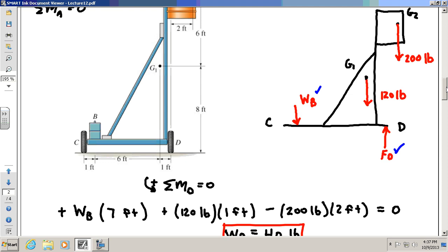No. I think he or she did the correct calculations. There's nothing wrong with it, right? But usually what we like to do is put a safety factor in things. I'm thinking to myself, okay, it takes 40 pounds. I'm going to throw a safety factor of 3 maybe and put 120 pounds at B, okay?